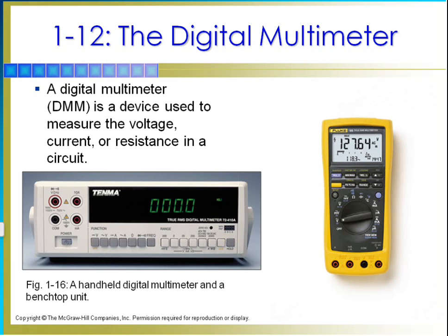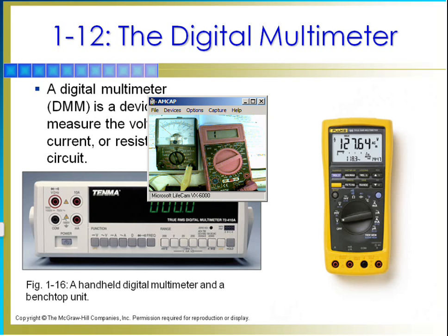How do we measure this kind of stuff? Well, we use multimeters. Now, here we're showing the digital multimeter, and let me bring my meters back in again. Here I have two different multimeters. I have a digital right here. These are my personal ones. And we have my very old analog mechanical movement multimeter. Now these meters will do voltage, current. The voltage they'll do is AC and DC. They'll do current for AC and DC. They will measure resistance. They're handy tools.